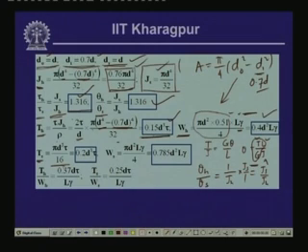T by J equals tau by rho. From that we get pi d cubed tau by 16, which is equal to 0.2 times d cube times tau, and the weight of the solid shaft is equal to pi d square by 4, the cross sectional area, times length times unit weight, which comes as 0.785 d square L gamma.